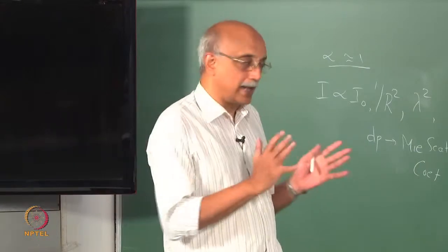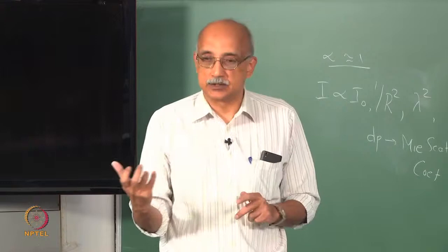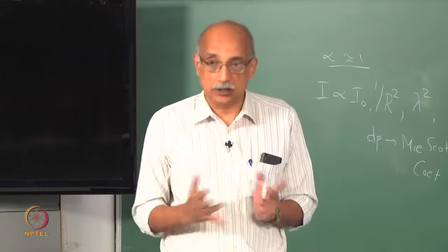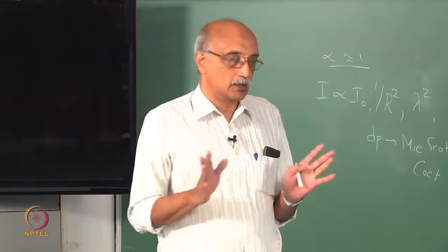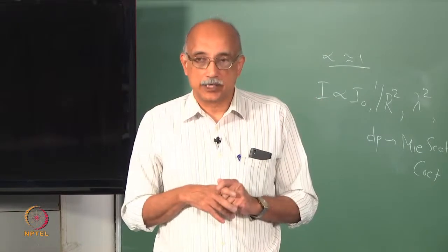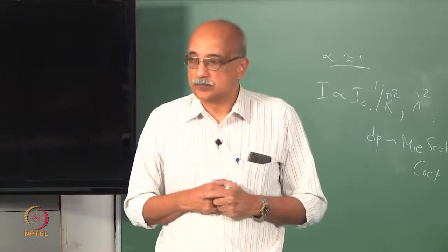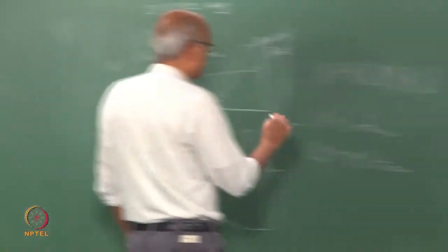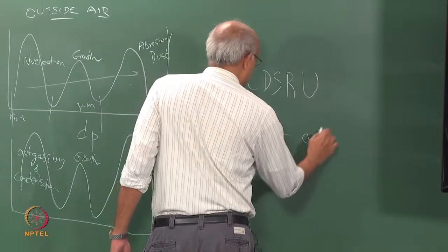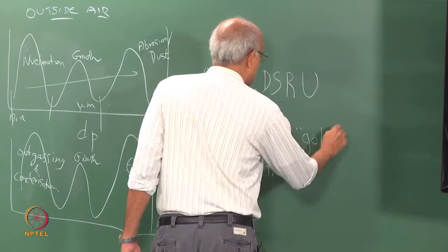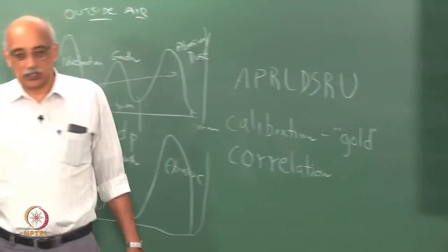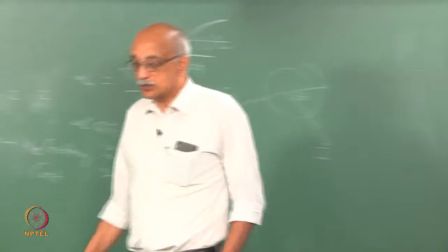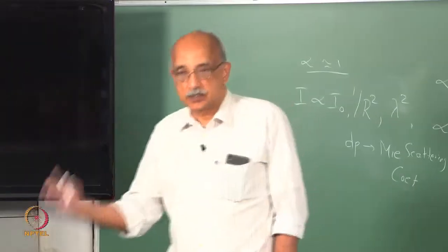So, if you want to calibrate a sensor that you are using for particle counting, there will be a standard that you have to compare to. Now, it is called a gold standard. So, calibration is done against a gold standard, which is typically an external standard that is maintained by a standards laboratory.